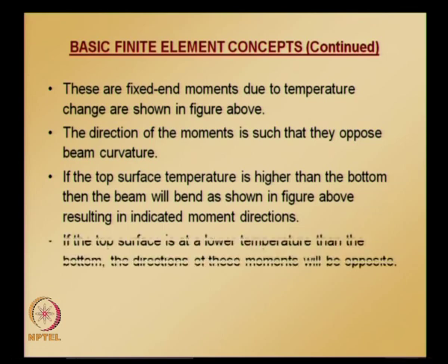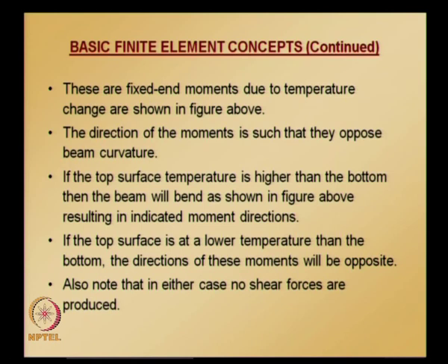And these points I just mentioned now. And please note that the direction of moments is always such as to oppose the beam curvature. Okay. And in both cases, whether the temperature of the top surface is higher or lower, no shear stresses will be produced. So now we know the fixed end moments,